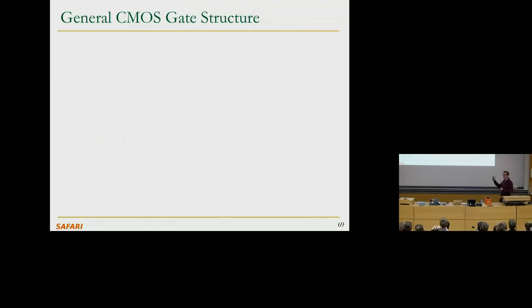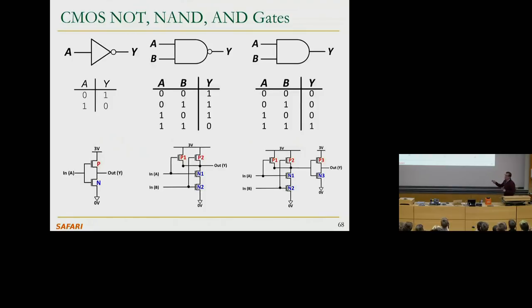Okay, this is our level of abstraction. So basically, similarly, you can do OR, right? I didn't give you OR here, but it turns out NOR is easier to build than OR. So you start with a NOR. This is not a NOR, this is an AND. What is a NOR? NOR is essentially a NOT OR. Basically, you take the OR of A and B and then NOT it.